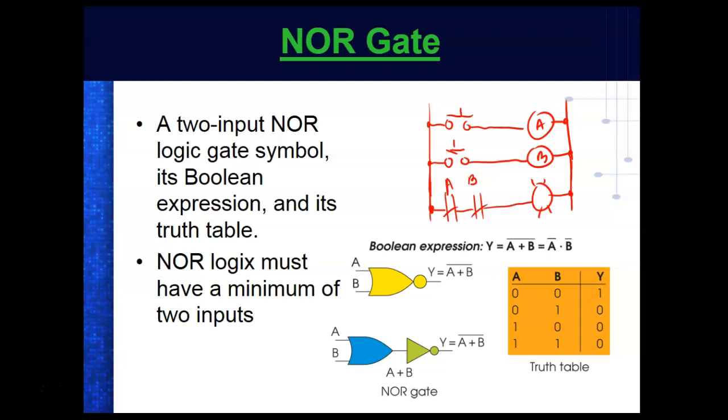And then we can combine logic. So I could come up here and do this. This is just the logic. And then I could come down here and do this. Of course, this wouldn't be any good. What we have here would be not A and B, or A and D. Of course, this down here would be true all the time. But what I'm trying to say is we can combine logic in a rung, and we'll see that all the time.